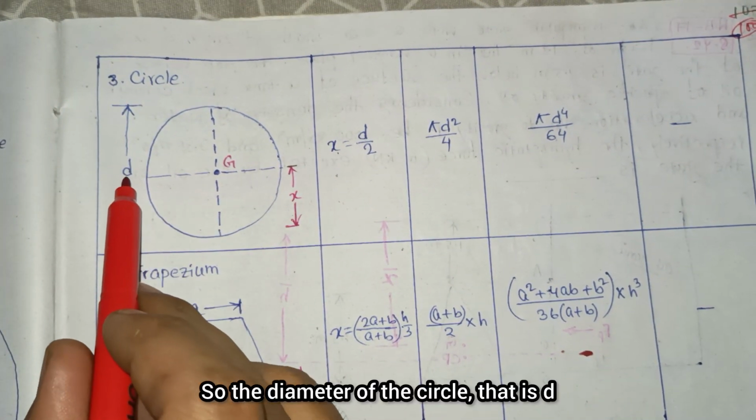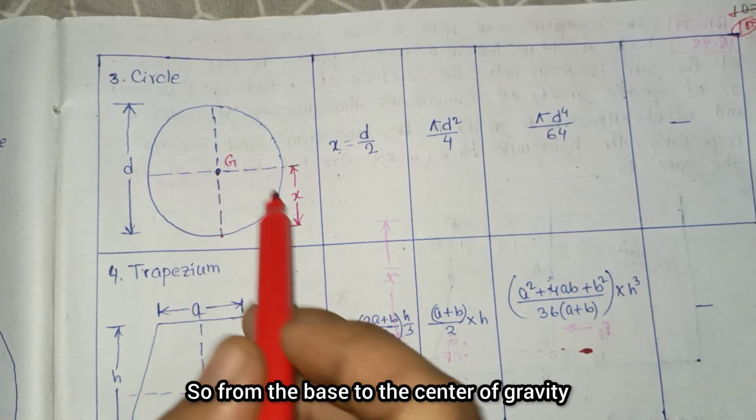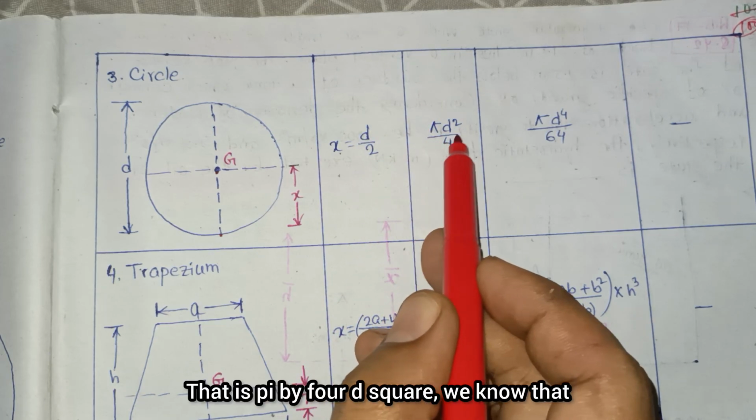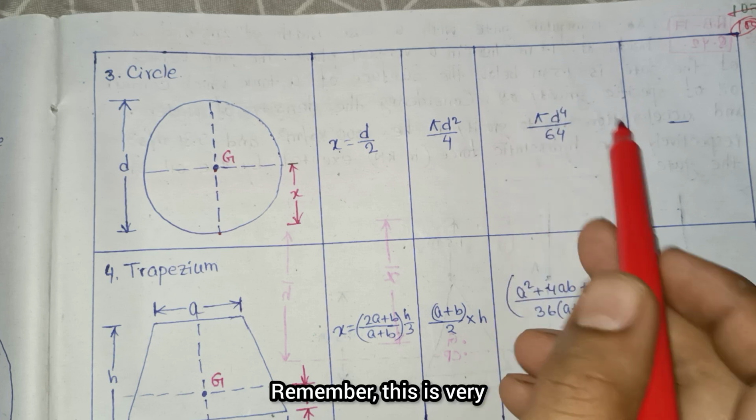For a circle, the diameter of the circle is d, and G is the center of gravity here. From the base to the center of gravity, the distance is x, and x equals d by 2. What is the area? That is pi by 4 d square, we know that. And what is the value of Igg? That is pi d to the power 4 upon 64. Remember, this is very important for the circle.